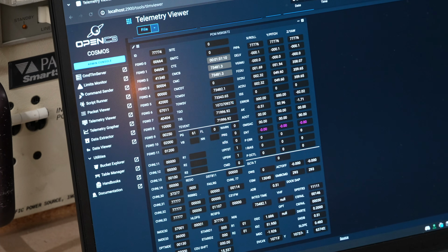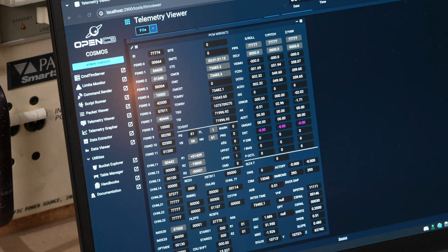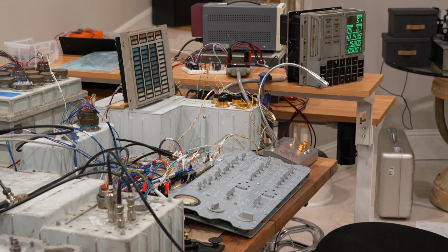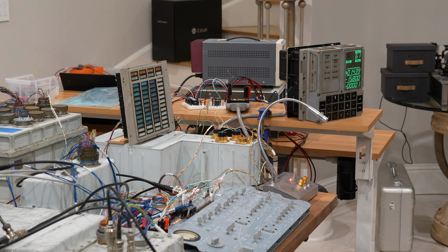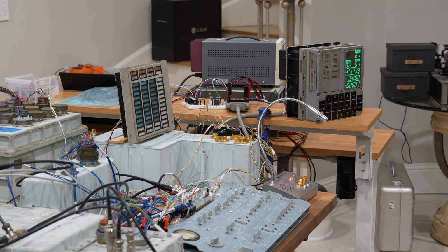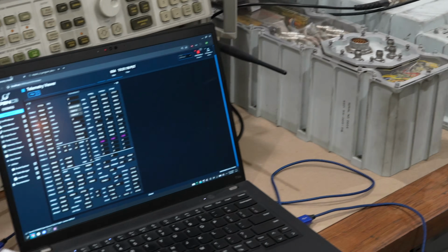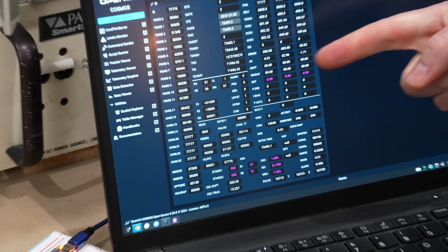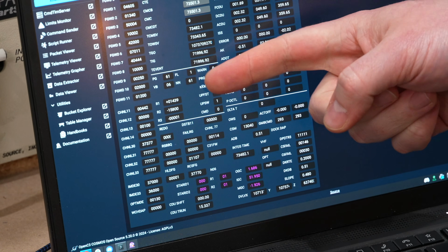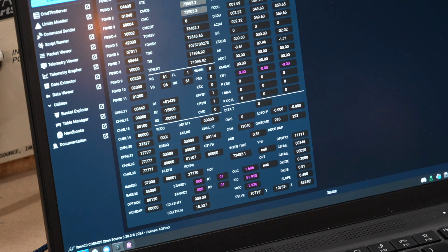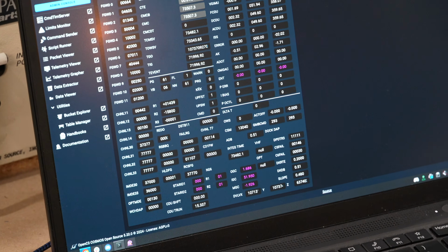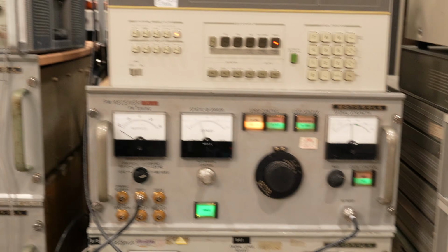There you go, and I heard the DSKY say something. Yeah, it came through. So we're reading remotely from the DSKY over here. Program 61 flashing 1439, 15,000, something like that, and we have the same thing. Yeah, the FL indicator right there means that the verb and noun should be flashing, and it has the same numbers. It came down through telemetry. I see my bits coming here.